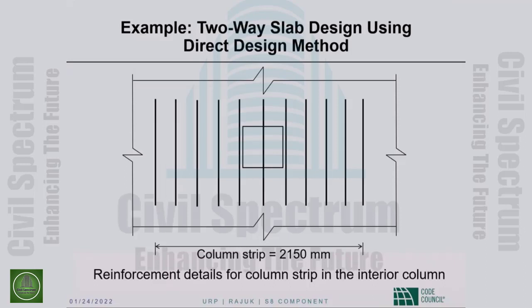But bent bars require a certain depth. I don't know that there is a code prescribed depth in general, but I think in the case of slabs, there actually is. I forget now, 6 inches and 16 times the bar diameter, something like that. There is a provision. You cannot use bent bars even if you want to, unless your slab thickness is beyond a certain minimum. I cannot remember whether it is 6 inches or 8 inches.